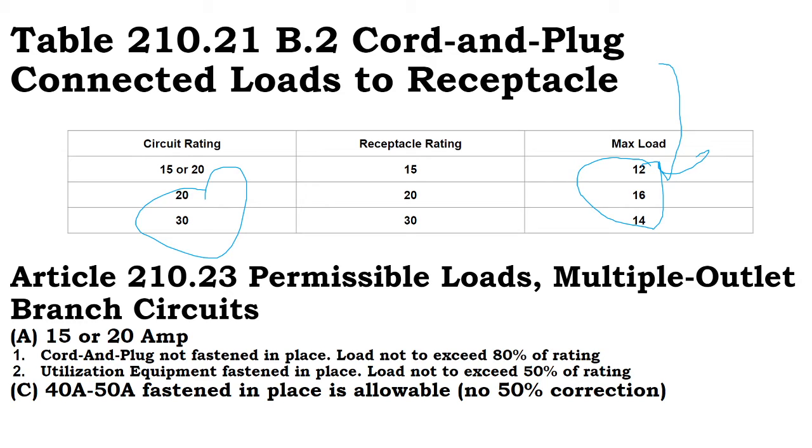If you have a 20 amp branch circuit for microinverters, they're only allowed to get up to about 16 amps before you have to add another circuit or breaker. If you got all the way up to 20 amps operation, then the breaker would trip and it wouldn't be a very good system because the breaker would be tripping all the time.